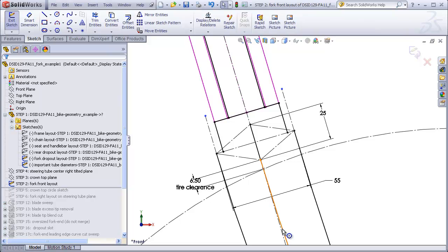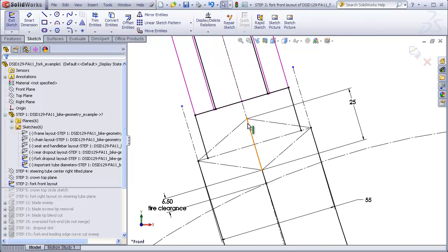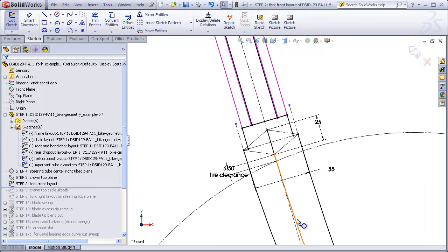This portion of the inner and outer guide should go straight through this area before it starts curving in this area. By going straight, this is a straight line from this point to this point, it makes sure that the outer guide and the inner guide both are in the same position when they pass by this point. That will be important later on when we're trying to make accurate projected sketches. So just trust me on this one. Make this portion straight before you do any curving on this inner and outer guide.